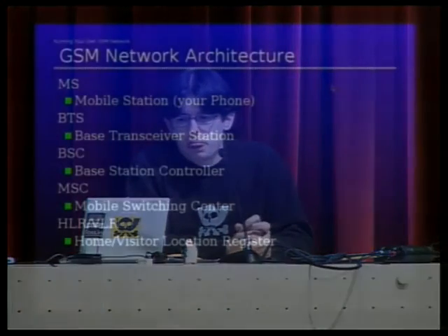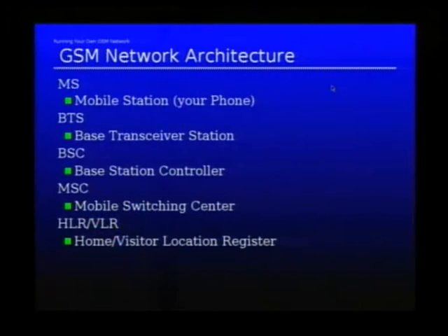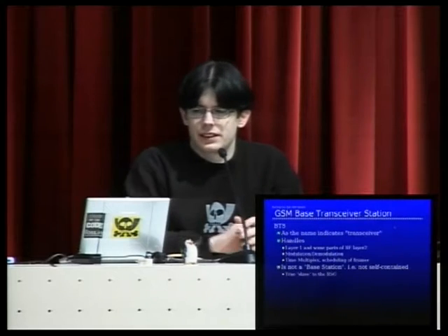We have a mobile station. We have a base transceiver station. It's important to say the base transceiver station because it really is a transceiver. It's not a base station. If you say it's a base station, you think of something that actually can interact by itself with the mobile device, and that's not the case. It's just a transceiver. You have a base station controller, which implements all the logic, a mobile switching center, and so on. I'm going to talk a little bit about what these individual parts do.